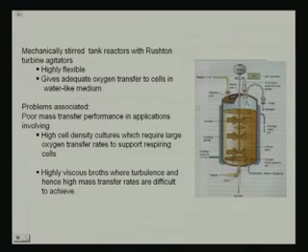So, if we are talking about these problems, then this high cell density culture, which requires a large oxygen transfer rate to support the respiration of the cells, cannot be satisfied with this type of reactor system. In a highly viscous broth, where turbulence and hence high mass transfer rates are difficult to achieve, we should not use this type of reactor system.